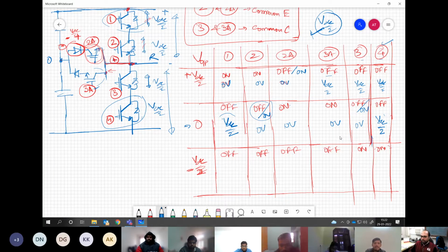Yes. Good. Now, when we are trying to have this voltage output of minus VDC by 2, what is the voltage blocking requirement for this end? Plus VDC, which means we must turn off both 1 and 2 because the rating is VDC by 2. We cannot avoid this. These two must be off and these two are on, so 0 volt is coming over here.